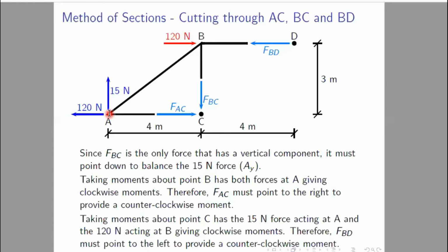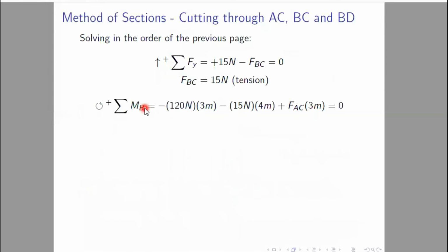So while choosing the point about which we are taking moment, it is very important to understand which point to take. If you take the point through which two unknown member forces are passing, then there will be only one unknown member force left, so you can easily solve for that unknown member force using that moment equation. So that is very important.